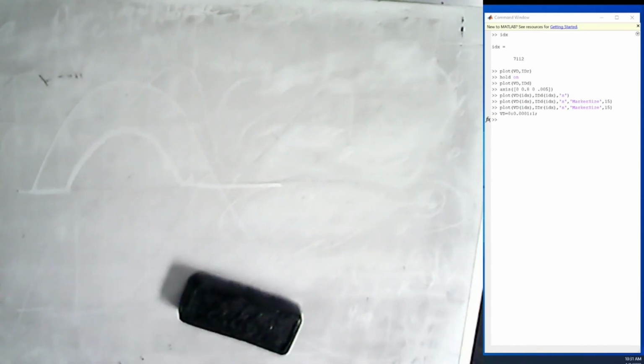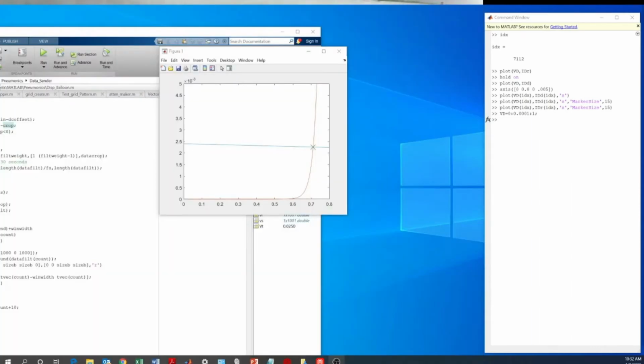And if you look at the plot that we have here, and let me put the plot back up here. We're going to go to our standard, and some of you in class have already mentioned this, but you come here and you say, for the vast majority of this, up until we get to really teeny tiny, look how small that current is. That current is in the microamp range. Up until we get down to the microamp range, okay, hundreds of microamps, up until we get to there, and even below that, it looks a lot like 0.7 volts.